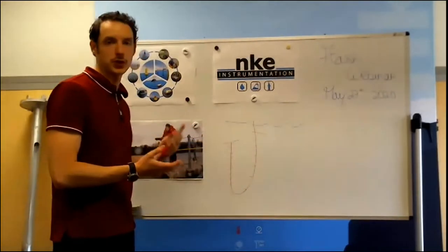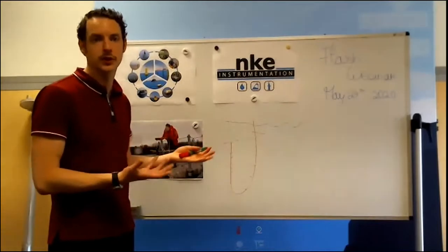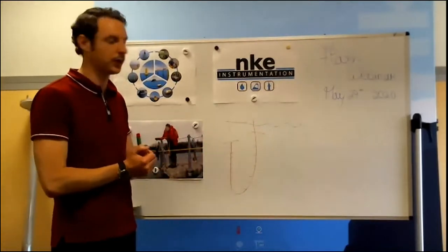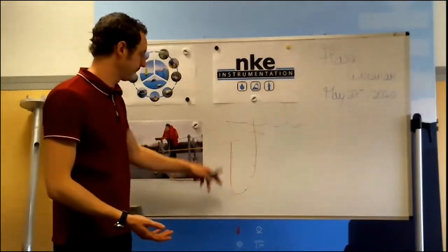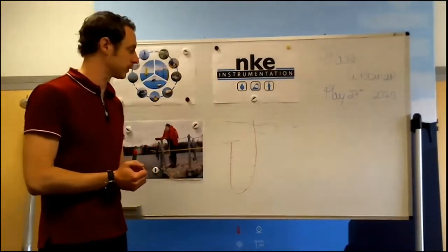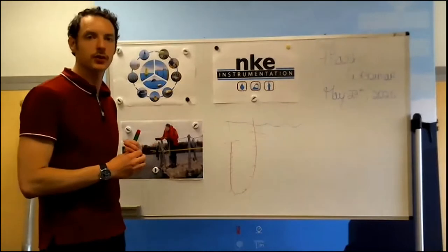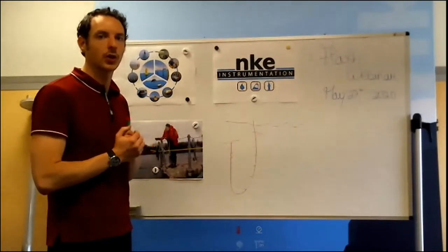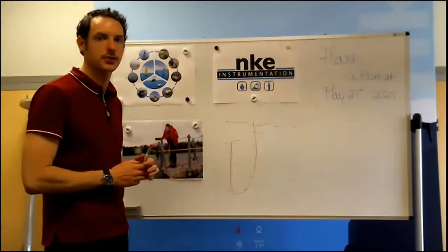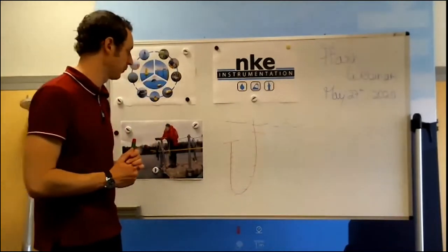So this could be a pressure condition, but actually also it could be a conductivity condition. For example, if you're in salt water, so just when it's in the water, it will start recording, and it will stop when it will be out of the water. So this can be an interesting solution if you have people going on the field who do not know at all how to use or how to manipulate an instrument. It's a zero training mode of use.